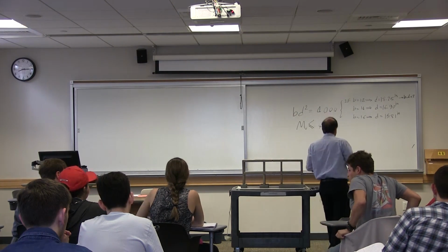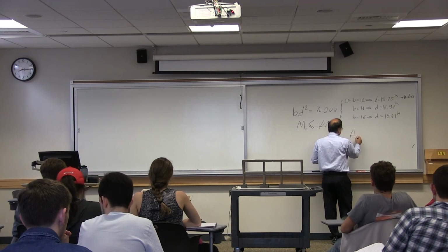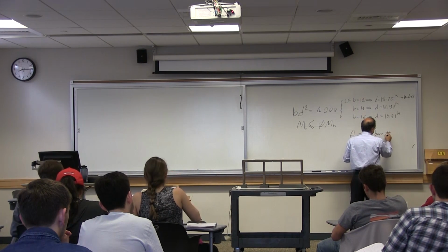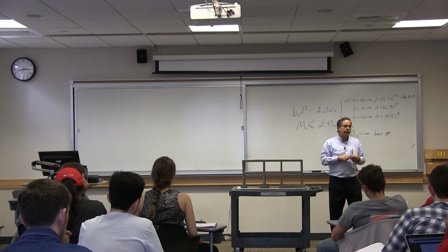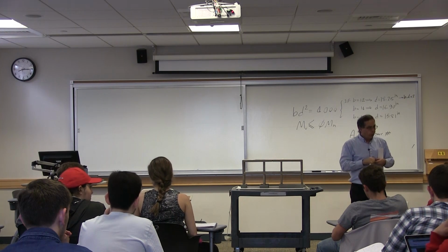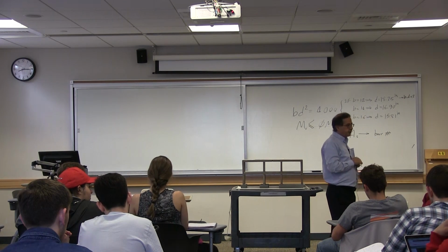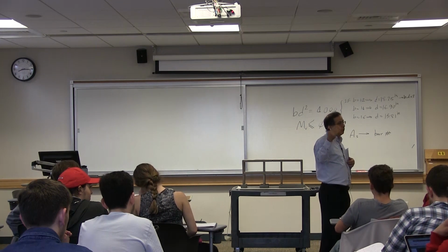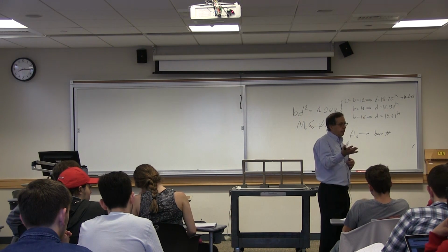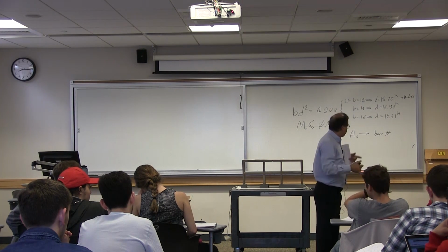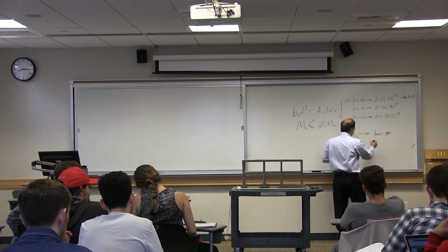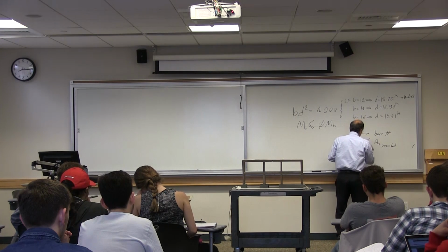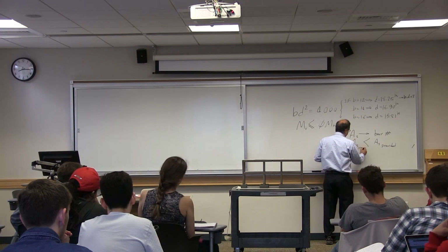Okay, so you have AS. From AS, you find bar numbers. So you want the bar numbers to be more or equal, correct? So then once we determine the AS and we find the nominal moment, if you are doing more rebars, your nominal moment is going to be phi Mn. So let's say you choose this one, and we say AS provided is larger than AS required.